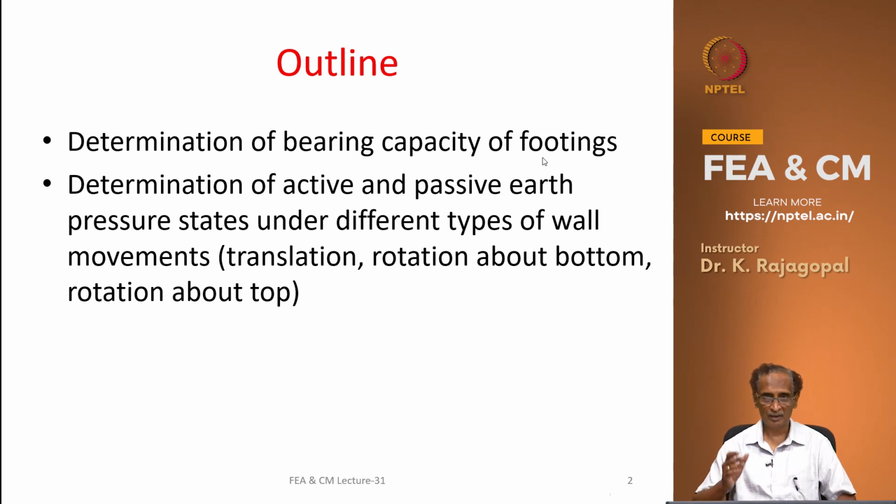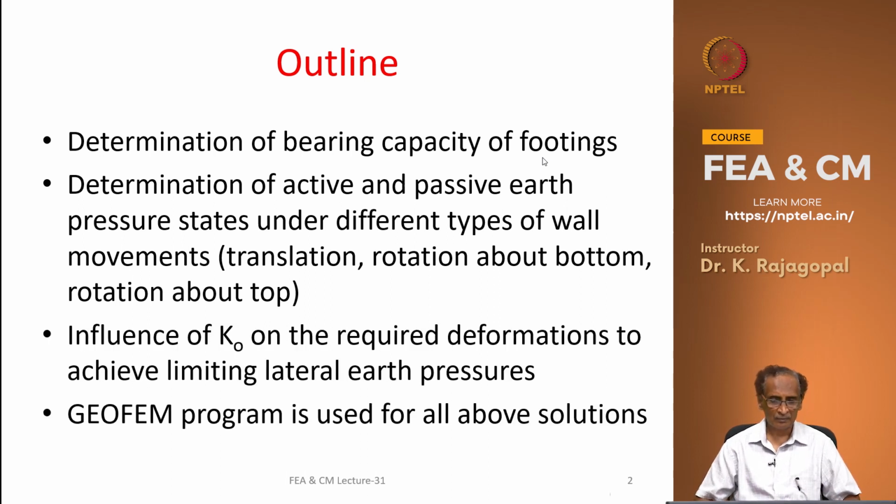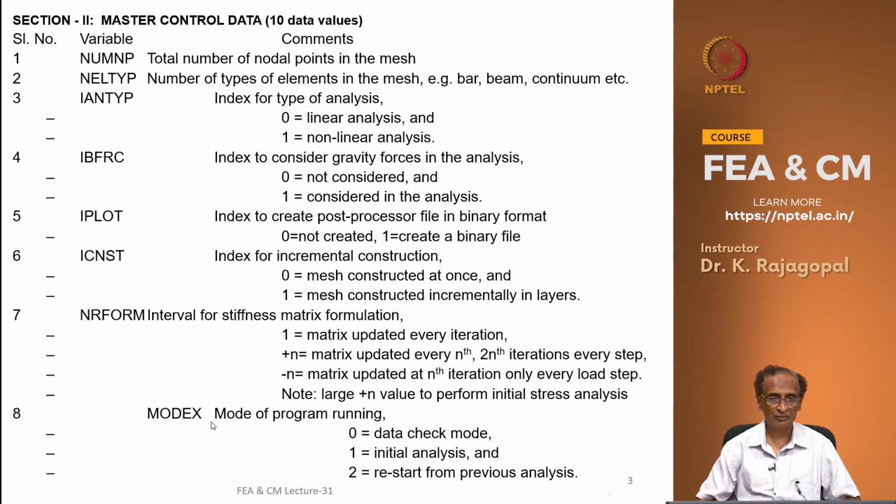And then we will also look at the influence of K naught, that is the initial earth pressure state, on the magnitudes of deformation that we require for achieving our active and passive limit states. And in all these, I will demonstrate the use of the GeoFM program that is going to come as part of this course, that you can use for doing all these analyses.